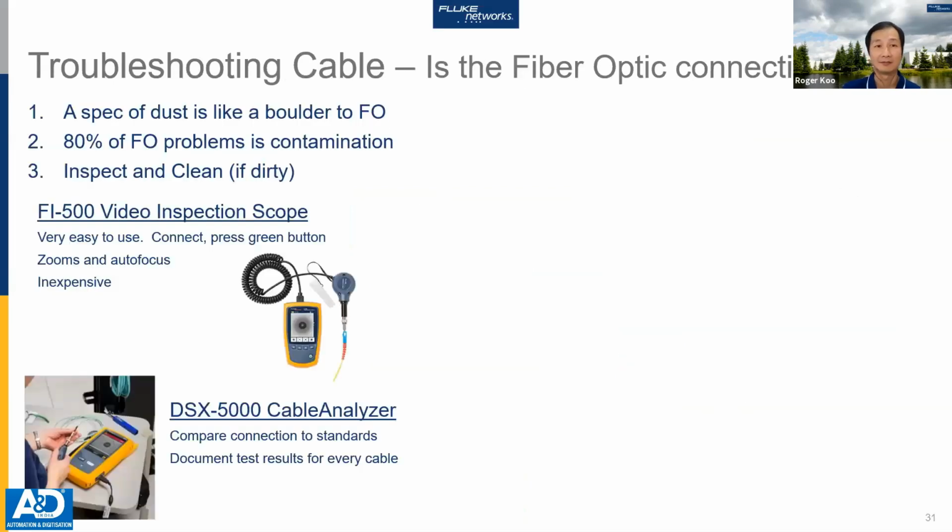Now, what about fiber? The number one issue of fiber is dust. A speck of dust is like a big boulder to the fiber optics. Now, 80% of fiber optic problems is contamination. So always inspect and clean as the first step that you should take.